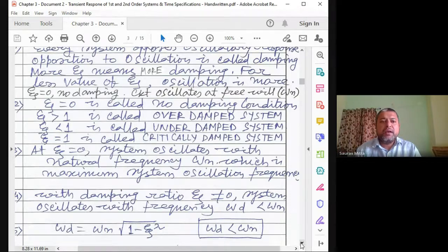So you people are confusing too much about steady state error. First thing you have to see output, and you should know how much is the input. So if I say steady state error, first you should ask what is the input. So input is the unit step. That means input is 1. And then steady state of the output. So when the output is changing, so output is increasing, whenever it is increasing in the linear graph, there you don't find the steady state error. You find steady state error after the output stabilizes.